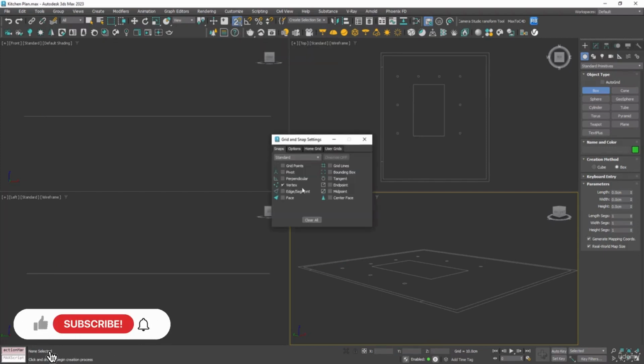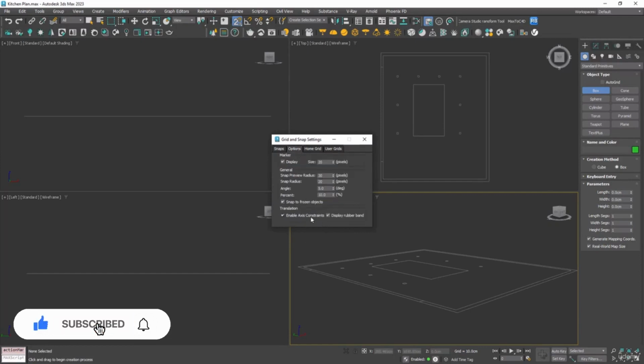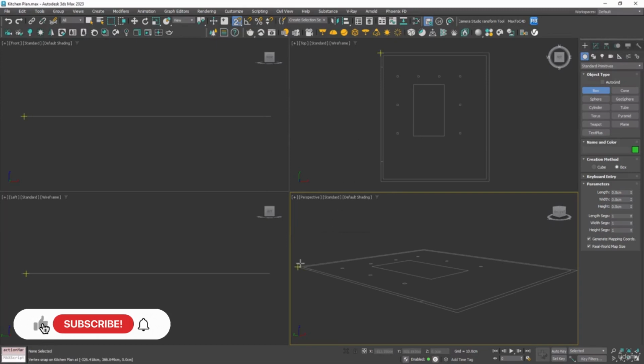And if you right click on it, notice that I only have Vertex selected, and that means that our box will only snap to vertexes. And if we go over to Options, we have Snap to Frozen on. This is what we want to be using. And we've got Enable Constraints on. So set up your snaps like this. And then when we click and drag, you can see we are snapping to our floor plans.